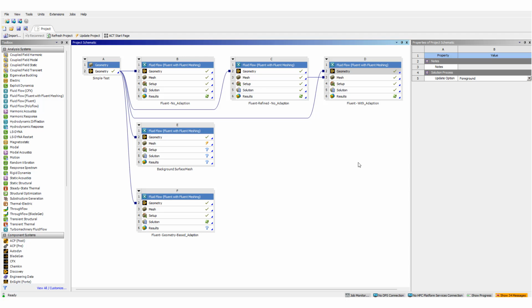Before starting, it is very important to know that we need a profile for auxiliary geometry that we use just like an envelope on the locations, or maybe for the whole domain, where we want to have the mesh adaptation based on the geometry. So we use a surface mesh that I created from the volume mesh.